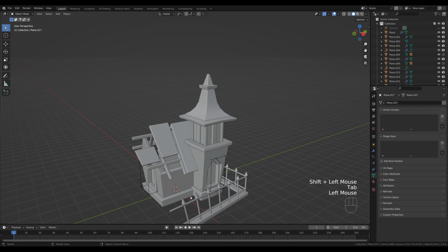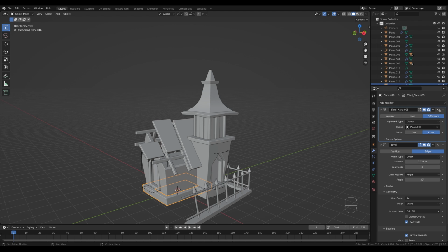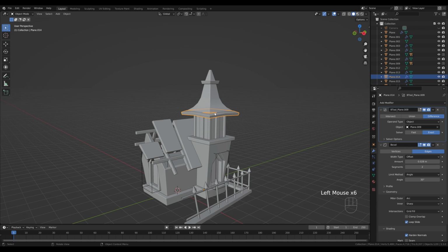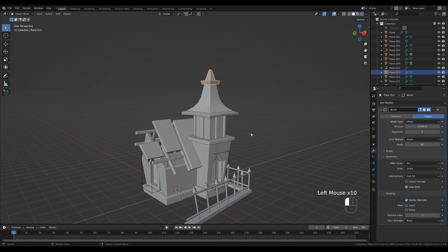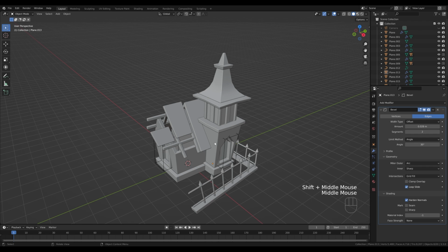And if some of these reused parts are misbehaving, that might be because when you duplicate the geometry from an existing object, it will get all the modifiers the original object had. So if you look here, there's a Boolean modifier from the window, so we can just remove those from these new objects. We don't really need them, of course. That's just to keep things a little bit more tidy. And now to add some additional details, you can just shift right click on the wall to place the cursor.